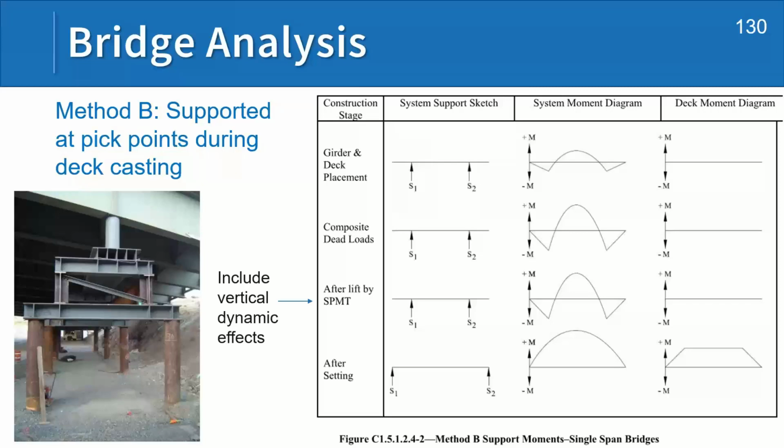And the answer is it does quite a bit. When you lift the bridge in the SPMT, you'll see the moment diagram. The deck sees essentially no tension when you lift it. The only tension of the deck would be due to dynamics. So it's a significant improvement.